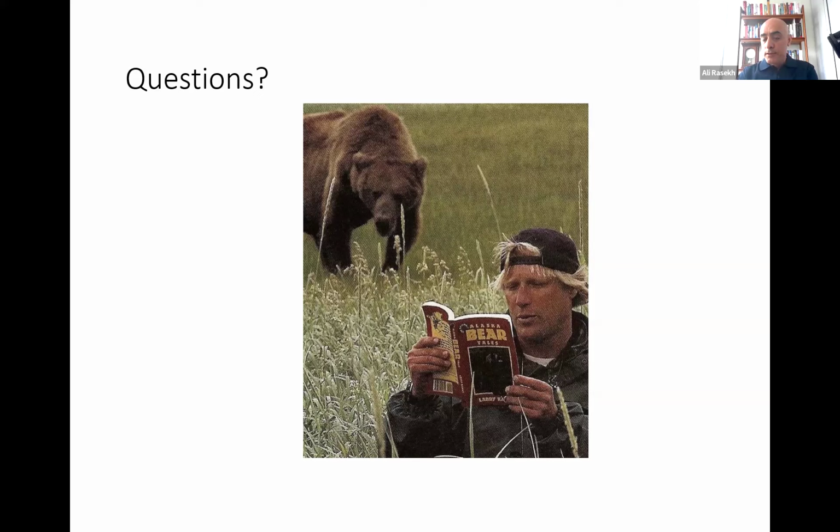BCs, yeah, we used a large model because the way we assume the waves are coming towards the structure is from the bottom up, which is a generally used assumption, but which might not be real. When you imagine that the earthquake happens at a distance and the waves come towards the structure, it's not really bottom up.